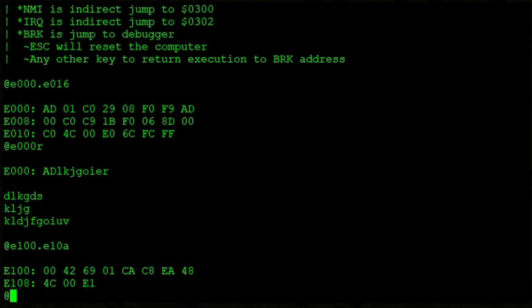So the actual program, just for testing it, is quite simple. It has a break instruction followed by a buffer byte. The processor views the break instruction as two separate bytes, even though it's only a 1-byte instruction. So I have the 42 in there just as filler for my assembler.